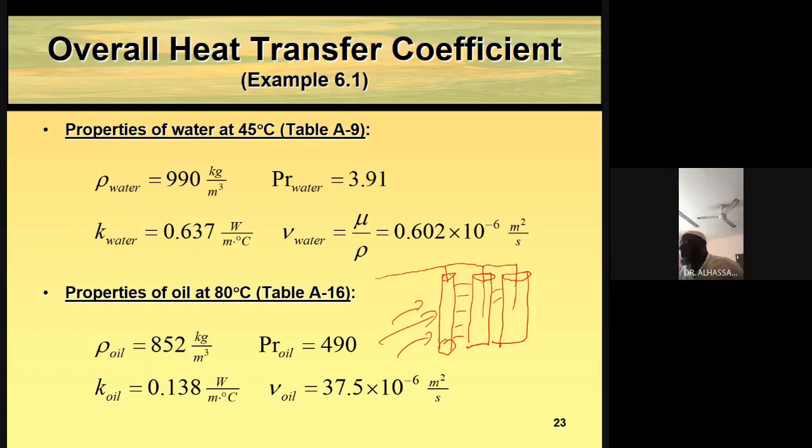So this will be perpendicular. This fluid is moving downwards, and then the cold air is also moving in this direction. So it cools down the fluid. Now the fluid will be collected somewhere over here. Then it goes to the engine again. So a car radiator is a very typical example of a heat exchanger.